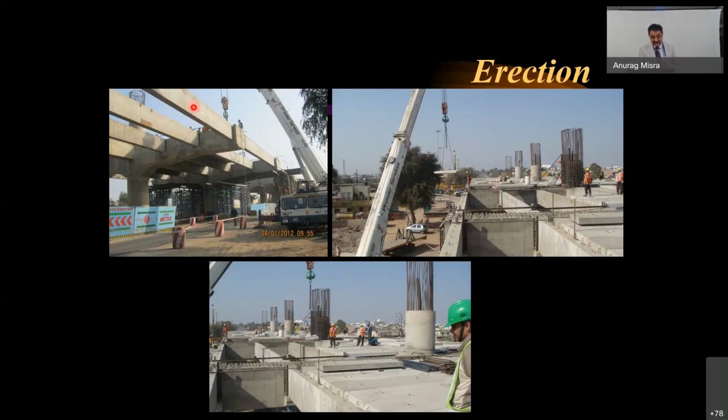which are designed exactly the same way in all this stretch. The slab size was the same, the beam spacing was the same. So the same slabs were coming, and these are already resting on it. There are some holes which would be used for tying the reinforcement and doing the stitch concrete. So this whole operation is completed. You can see it clearly showing here. So this is coming, and then that is placed here. Once these are placed, you can do a finishing concrete of very small thickness, so that the whole floor becomes one unit.